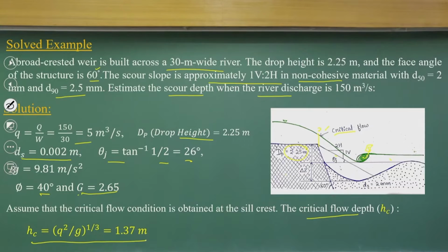in terms of Froude number equal to 1, and we can substitute V equal to Q by H. So, you can compute these equations at the critical flow, which will come with a Froude number equal to 1. You can compute it easily, we just have to remember these things.